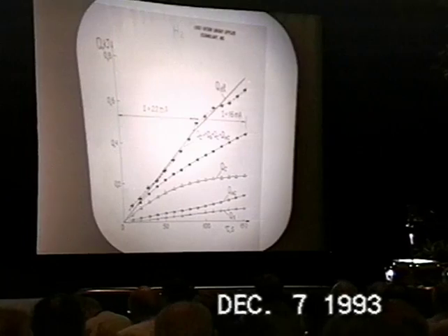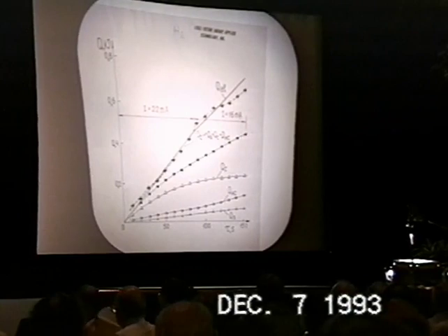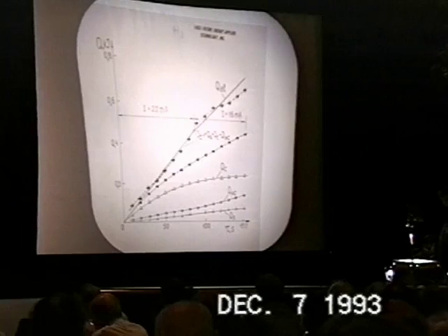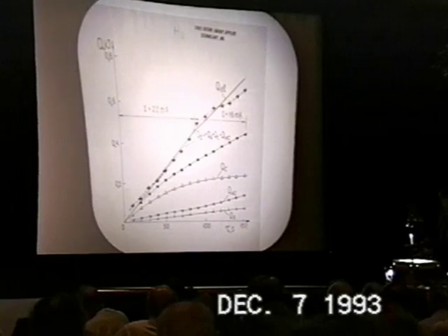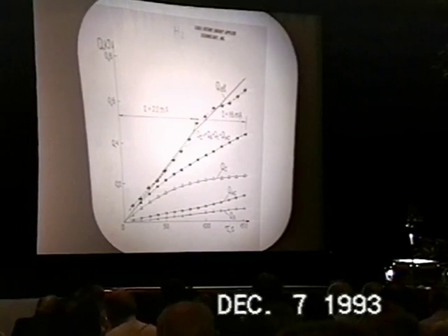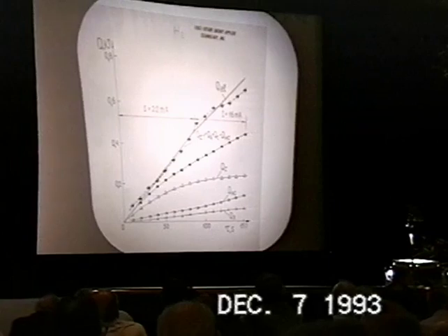So looking here, one can see the precision of this calorimeter is around 10%, and the estimated precision of the calorimeter varied from 3-5% in low energy, so up to 3-5 kilojoules it was 3-5%, and from 5 to 10 kilojoules it was about 10%.